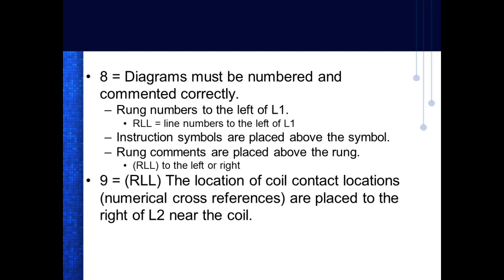What we're going to find out is that the PLCs past the 500 series all require you to give these guys names, right? You understand that? Because now, if you give it the same name, it'll give you an error. Y'all notice you can't give another address symbol the same name. The only way it lets you repeat the symbol is if the address is what? Exactly the same. So it takes care of you.